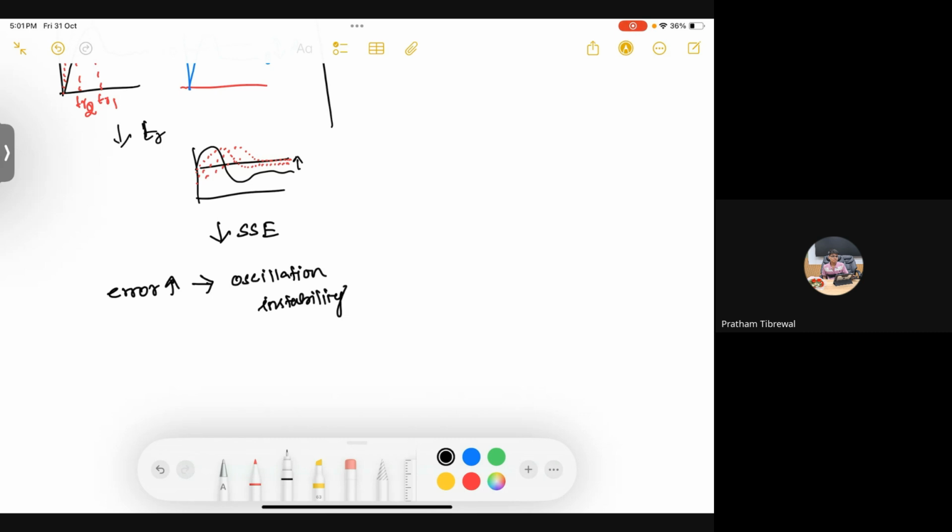So if your system has a larger steady state error, for example, this is 10, then your gain will also be proportional to 10. All of a sudden, if you pull the system from one point to another point, which is a very large set point, then this may push the system to the verge of instability. This is one disadvantage of the proportional controller.